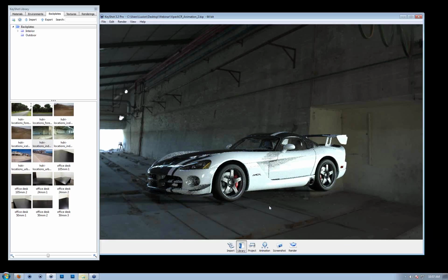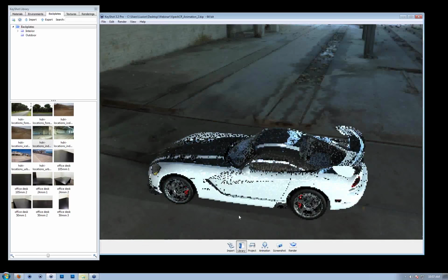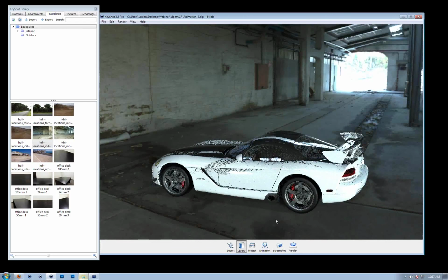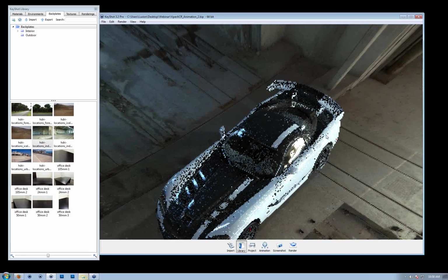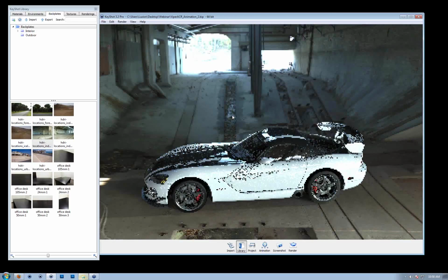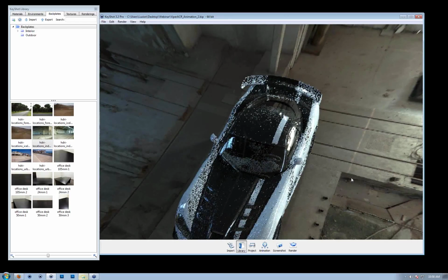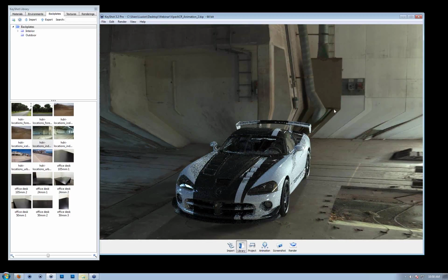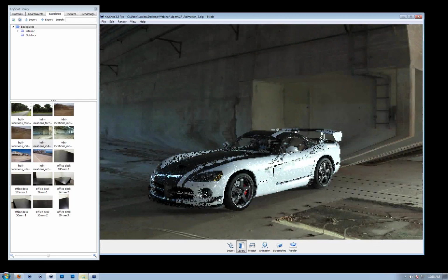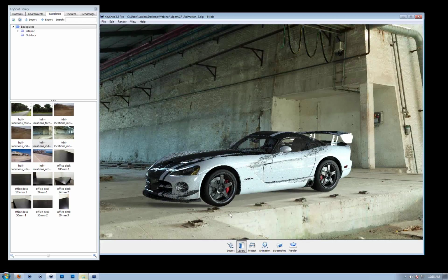You might also notice that this isn't how your environments typically look. Environments usually look like this, where when you move around with the camera, it looks like your model's floating above the ground, and what you see under the car is constantly changing. But if you hit the G key, G as in ground, it smashes the bottom half of the environment up to the ground level so that it plants the car, which helps. Of course, environments are spherical, so it creates a strange distortion effect. But we're using a backplate anyway, so we don't care about that.